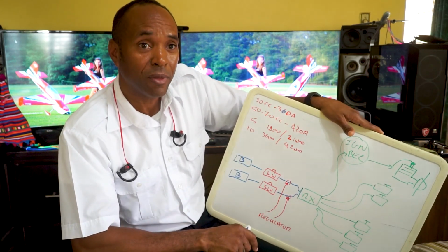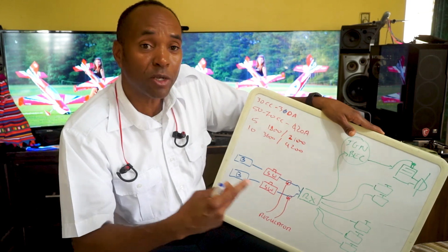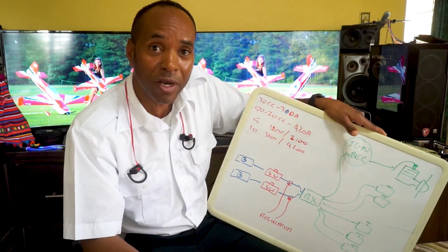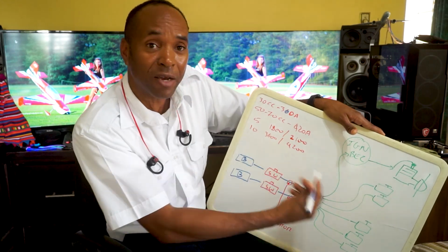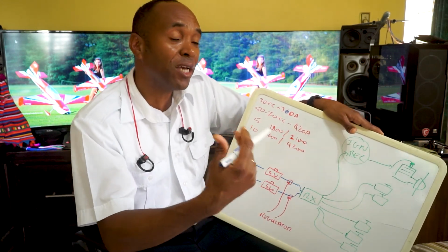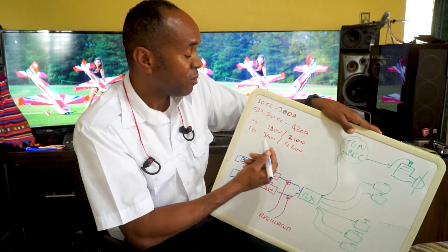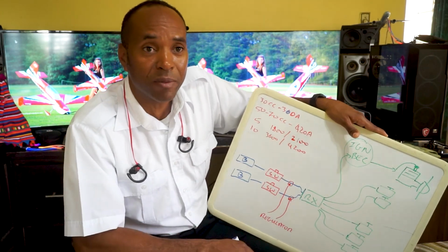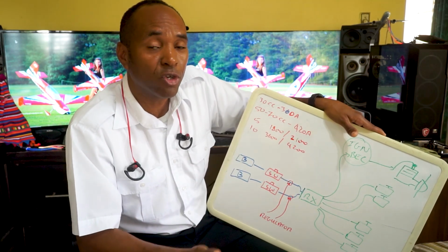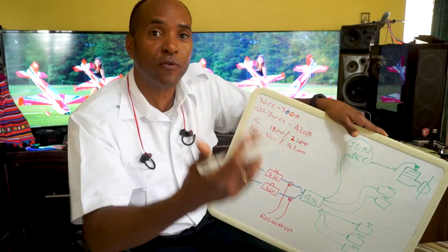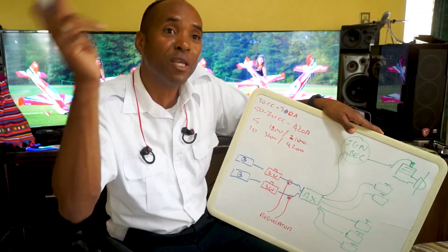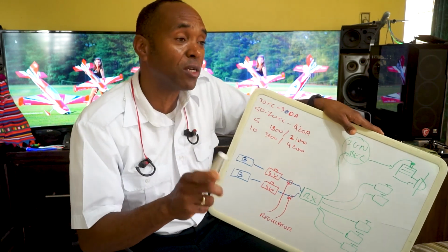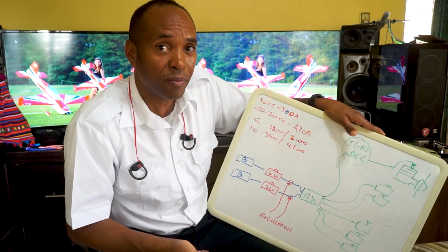for the day, right? If you want to push to 10 flights, you're going to have to either recharge, or change the battery, or go to a bigger battery that can take everything. The battery must exceed whatever this is. You're going to multiply it by 150% basically, or somewhere there, to make sure you have enough capacity so that you have 25% reserve when you finish, right? That is very important, or else you're going to run out of battery capacity.